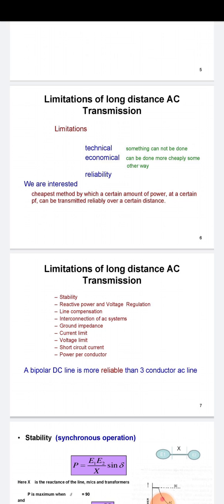The corona effect tends to be less significant on DC conductors than for AC. This also leads to the choice of economic size of conductor with DC transmission. Then the other factors that influence the line cost are the cost of compensation and terminal equipment. DC lines do not require compensation, but the terminal equipment costs are increased due to the presence of converter and filter.